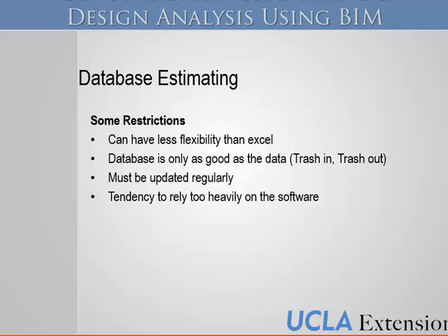So the smart thing to do would be to harvest that schedule of values data, then compare it to the budget data. Obviously the schedule of values is going to trump because that's what it actually costs. And so you can see, we've only been budgeting $80 a cubic yard for concrete, but really it's looking more like 100, 120. So that would need to go into the database now at 100, 120 a yard.